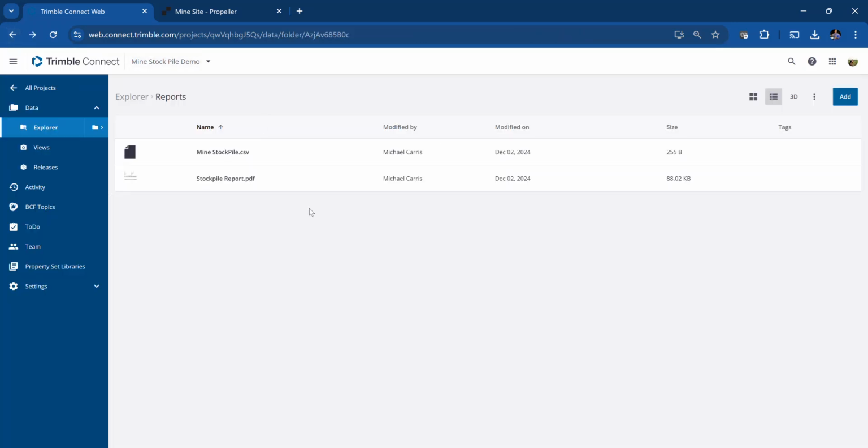So again, just showing you this connected workflow of Connect, Trimble Business Center, Stratus, a lot of different tools you can use to do this, but hopefully that gives you an idea of some other methods of getting these large data sets from one program to another, and using them to extract stockpile volumes and use that extract stockpile volume command.